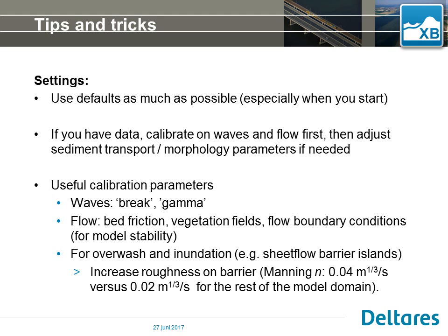Moving ahead, if you're running a model and you have data to calibrate with, then it's really best to calibrate on waves and flow first, the drivers, as it were, of the morphodynamics at the beach, and then only after they've been calibrated to adjust sediment transport and morphology parameters to achieve the measured bed level response. There are a couple of useful parameters for these different parts of the XBeach model. For instance, for waves, the break parameter will define what breaker model is used, whether it's the Roelvink breaker model or the Roelvink and Daly model for instationary runs, or the Baldock or Baldock-Janssen breaker models for stationary runs, and the gamma value, which helps to define the intensity of breaking.